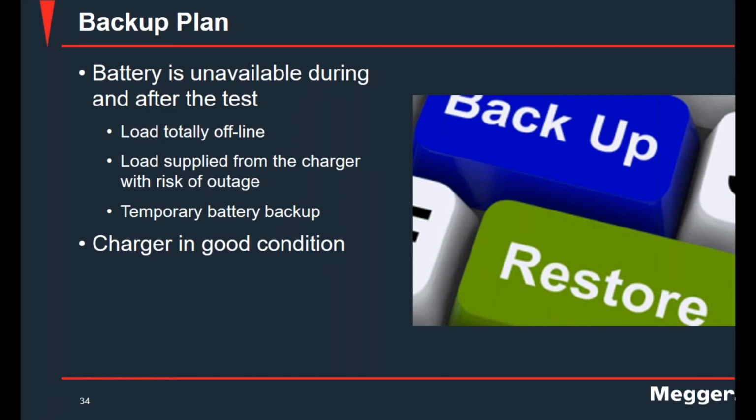And one more very important thing to consider is that you may want to have testing performed on the charger, or you want to have certainty that the charger is in good condition even before running the test. Because what if you finish the test, the battery is without any energy, and then your charger doesn't work? That is a very, very important consideration before running the test.